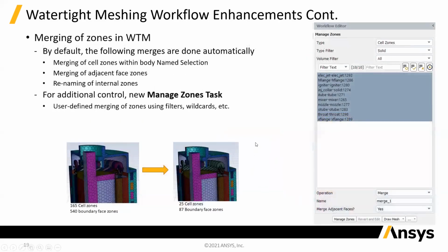Also in the watertight meshing, you can now merge zones. So there's a new option that will allow you to go in and do merging so that you've got much more control over the zones, so that when the mesh comes into Fluent, you've got the zones grouped together that you want for setting up physics.